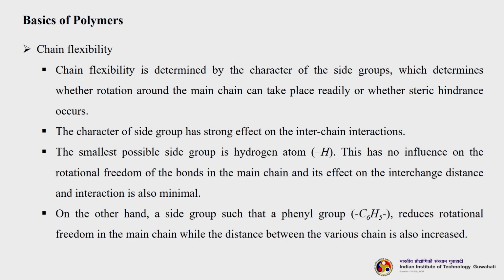Okay. So, for this you can impart some of the heterocyclic and aromatic groups to the main chain, so as to increase the flexibility. So, chain flexibility is determined by the character of the side groups, which determines whether rotation around the main chain can take place readily or whether steric hindrance occurs. So, the side chain is actually deciding whether rotation is possible or not. The character of the side group has a strong effect on the interchain interactions.